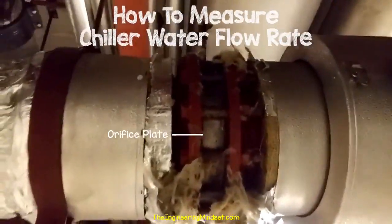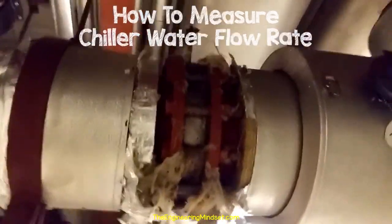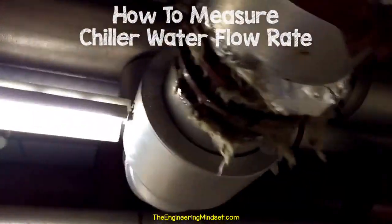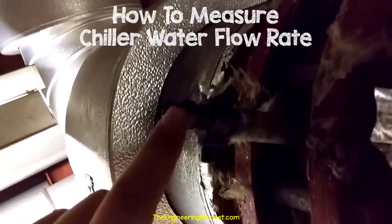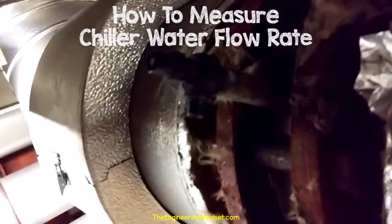Now these are likely covered with insulation, so they might be a little difficult to find at first, but you can identify them by spotting the 2 thin tubes which stick out of them. Now the tubes will be coloured, so one tube will be blue, which means this is the low pressure side, and the other tube will be red, which means this is the high pressure side. It will probably have these little plastic tags on them as well to help identify them.